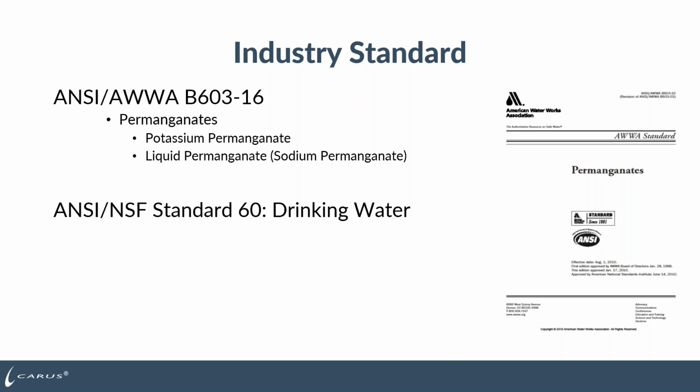The other standard that's really important is NSF Standard 60, which is testing done by the NSF group that certifies that permanganate can be added to a drinking water, and it establishes a maximum use level for both potassium permanganate and sodium permanganate that you're going to apply to a drinking water. So you want to ensure as a drinking water plant that you have a product that meets the NSF Standard 60, and it'd be nice if it also met the AWWA standard because that's a standard above the NSF of applying it to drinking water.